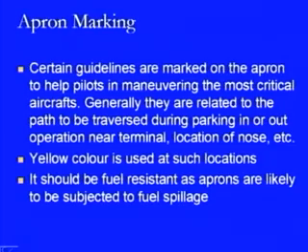Another thing is that the paint used should be fuel resistant, because there are all chances that during the filling of the aircraft or during certain other maneuvers the fuel may spill, and that may create a problem for such markings. So, that is one important specification of the paint used for markings on airports, that they should be fuel resistant.